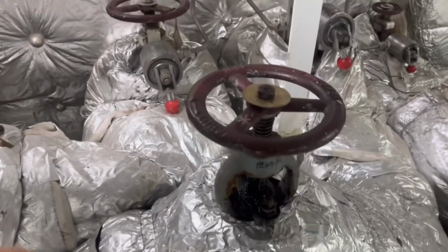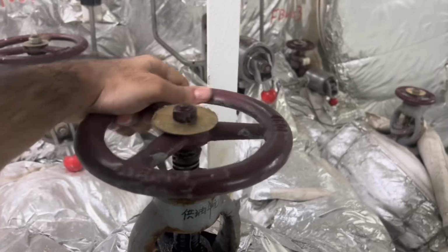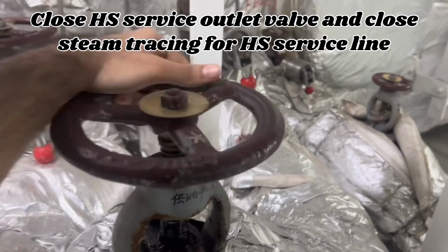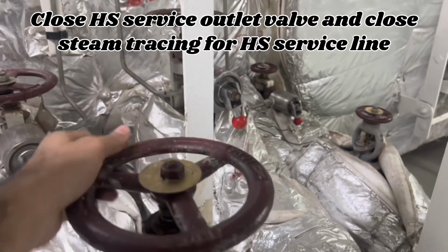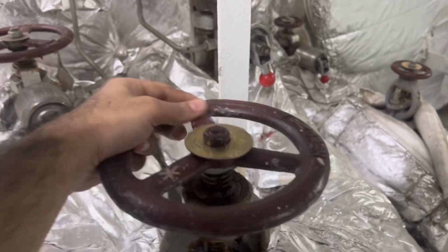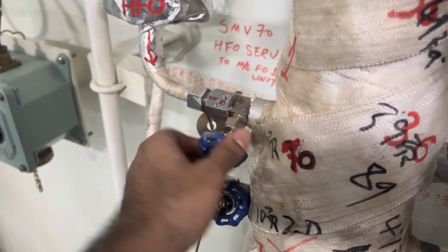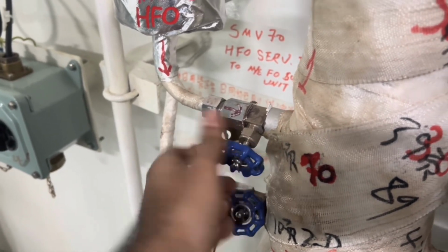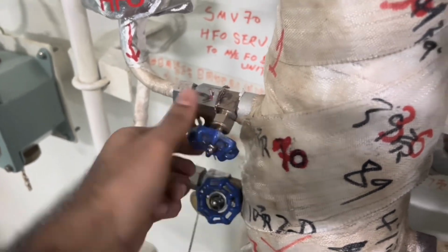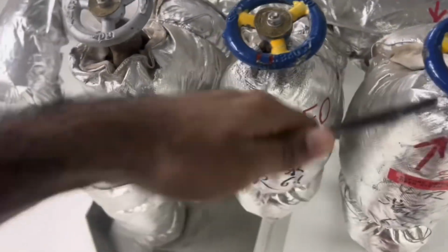So once the changeover has been confirmed to the low sulfur, we can close the high sulfur service tank outlet valve. And after this we will close the steam tracing inlet and outlet for the high sulfur oil. So now you can close the inlet of the steam tracing for the high sulfur fuel oil inlet, and then afterwards you can also close outlet. So after closing the inlet steam tracing, I will close the outlet.